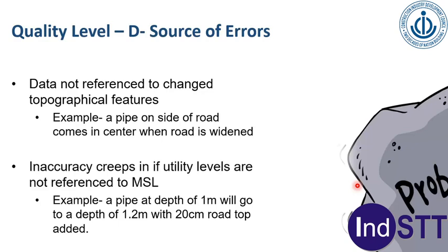As I said, if you really go to the list, there will be more than 17 to 19 different methods which are listed. But the fact is that in urban environment, the most commonly used tool is GPR, ground penetrating radar. This can detect both metallic and non-metallic utilities. It of course has capabilities and limitations. This session is too short to go into detail of it. The idea is just to give you an overview of SUV. There are a few videos which are referred here. You are more than welcome to watch these videos.